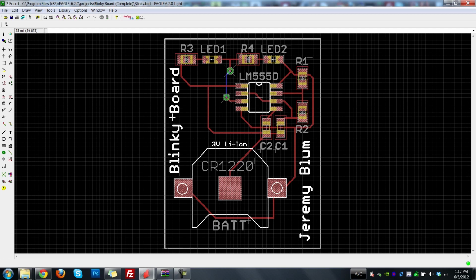One of the important things to consider here is we'll need to take some time to think about the size of the components that we're using. So there's the schematic view and the board view that looks like this. In this case, I used all 0805 size passive components, and that refers to the size of the actual component. But we'll talk about that a little bit later when we're actually doing layout. Okay, so this is kind of what our final project is going to look like.